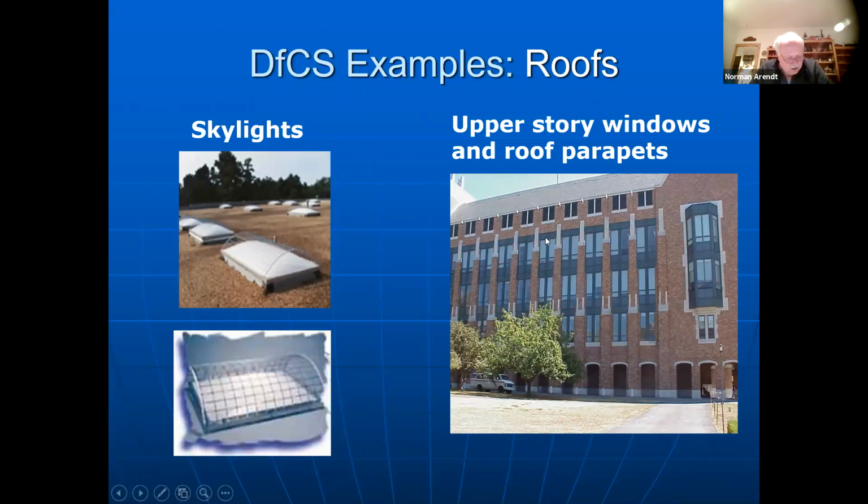Parapet roofs generally in the past have not been designed that high, but that would be a good practice, and that is in the OSHA standards now. If you design upper story windows that are 39 inches above the finished floor, all of a sudden you no longer have to worry about maintenance workers falling when they're working inside, because that height works as a fall protection alternative.